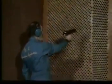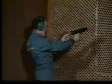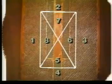To locate a leak site with the ultraprobe, conduct a quick scan, listening for an obvious problem area. If a sound pops out from the background noise, you may be able to get closer and pinpoint the leak site this easily. If a quick scan is inconclusive, divide the condenser tubes into testing zones.